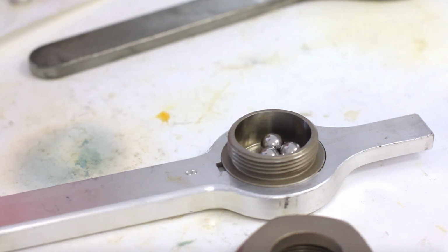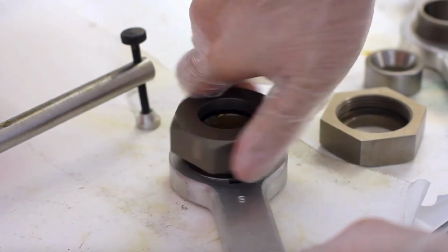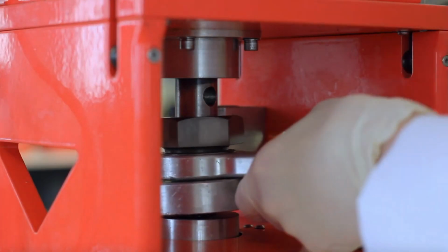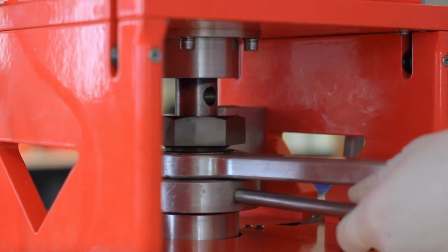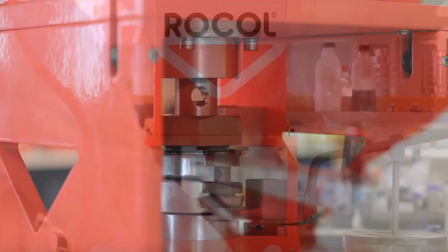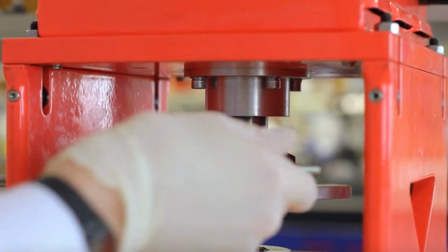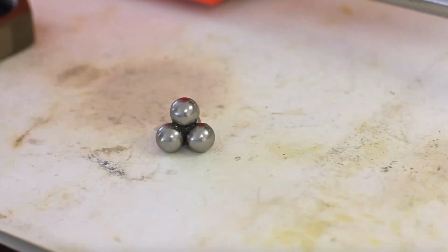He's got the three balls going into this thing. They're nesting in there. This little collar puts them in place. You load in your grease. And you have to watch real quick for where the chuck is holding the ball when he puts it on the machine, because you can't see the fourth ball. Right there. Okay, so you put it in the machine, you get it all aligned, locked into place, and you turn the machine on. Once you're in place, it starts spinning. It doesn't take long while it's adding force. There's usually some good audio as it's screaming. Sometimes you get smoke out of it. There it is. They're welded together.